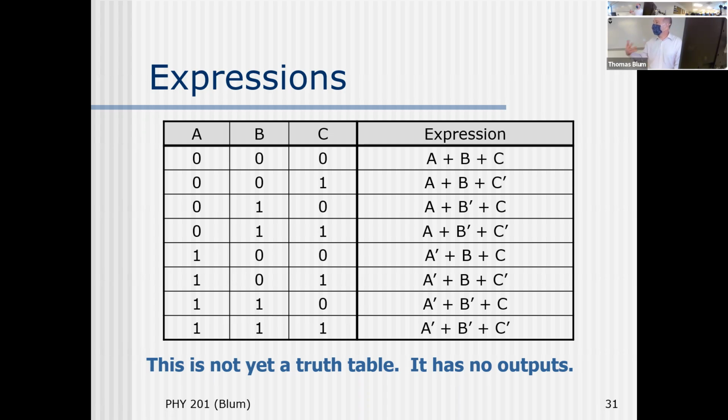So you're turning the pattern around. Now we're working with ORs. We want to make zeros. So now when it is a 1, we prime it. Before, you remember when it was a 0, we primed it because we were trying to make AND expressions be ones. So we wanted everything to be a 1. Now we want everything to be a 0. Okay.